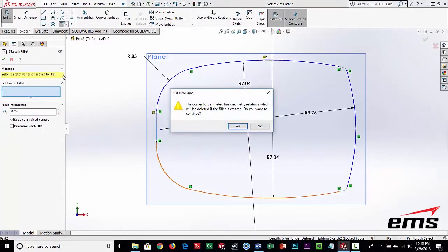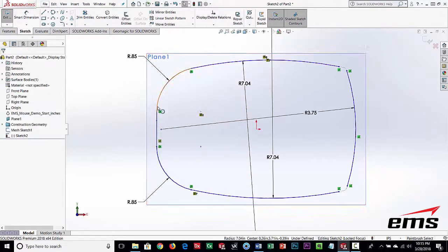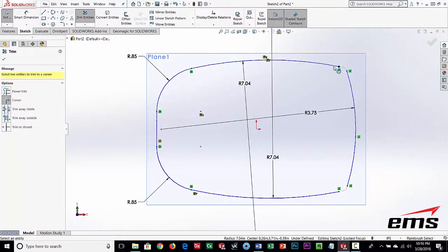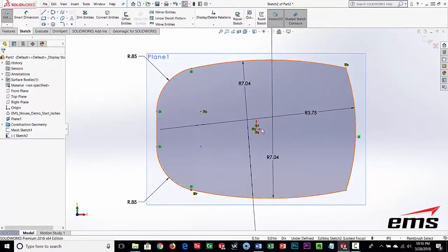Okay. And what I like to do is, the large fillets we'll go ahead and put in. But like I said, these small corners we don't want, because typically the part's been rounded off because it's old or worn. And if we do want fillets in there, we'll do that later, when it's a solid body. So the small ones, I tend to just model close to the corner and then just trim it out, okay? And again, we model the same way in Design X, and that's just a little bit of the technique.